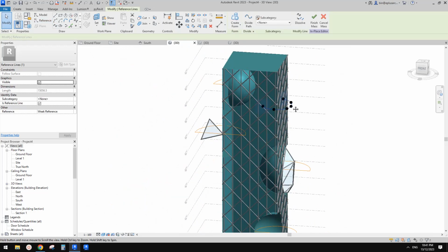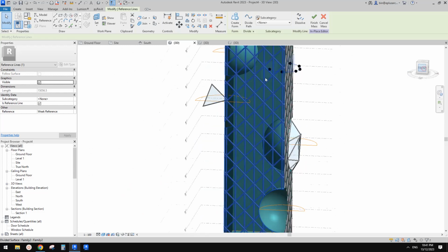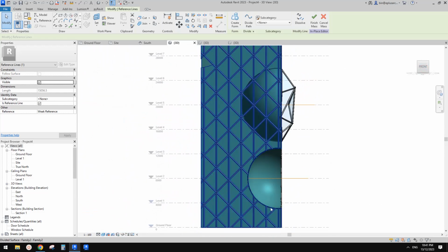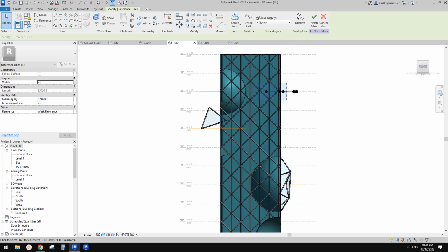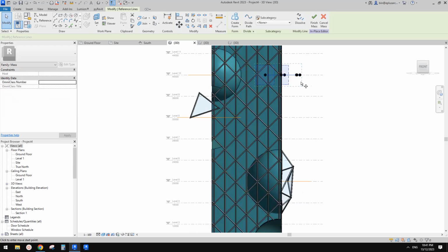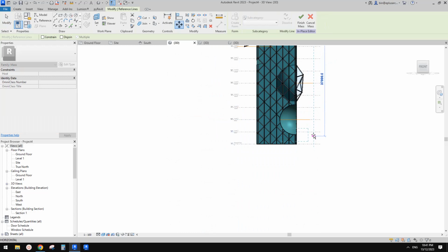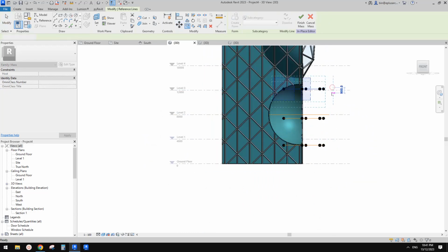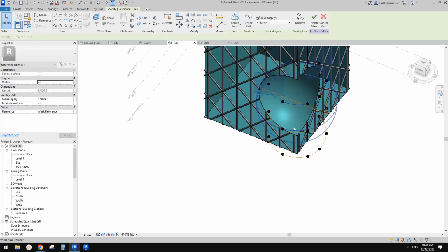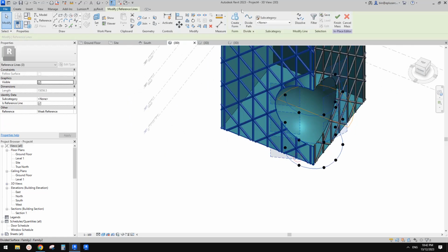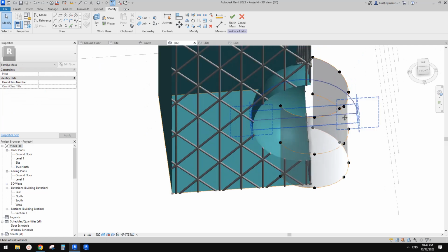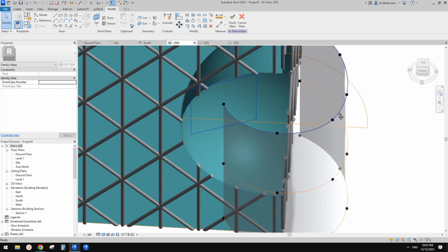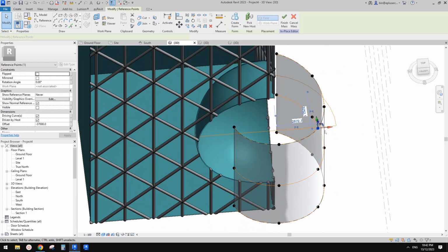And maybe I'll just move them down to roughly here because I want to cover this area. So select them. Spline through points are very flexible, so you can move them quite easily, and you can just copy them. Okay, and then we have three, right? 1, 2, 3, and you can create a form. Usually create a form first, because sometimes when you change the shape and then try to create a form, it won't work.